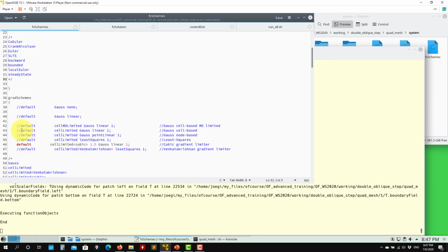I really like this method. But as I mentioned, just stick with this one. This is my preferred one, probably the most accurate one, and also is a little bit less sensitive to skewness, is the least square. But sometimes I have found that it can be a little bit difficult to get convergence with a tetra mesh, triangular mesh, low quality tetra mesh. But theory tells that this is a much better method.